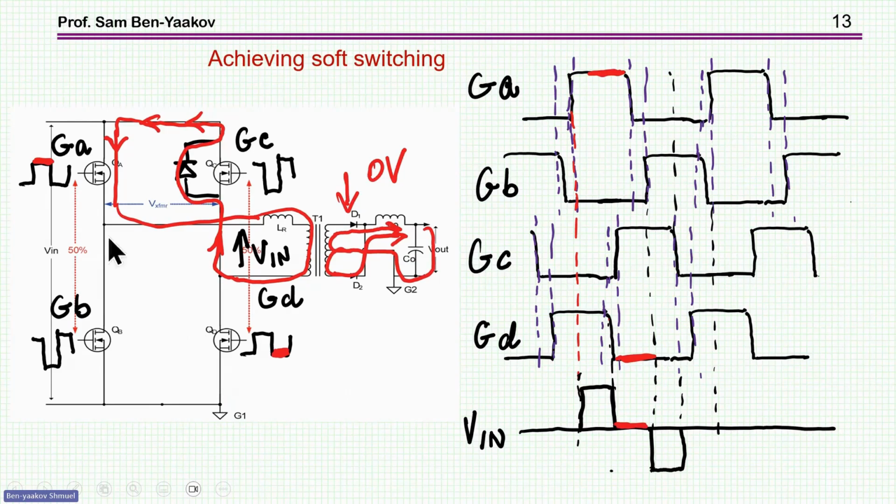So now this thing is locked. While being locked, very important to realize that the voltage at the output is zero, because now the two diodes will be conducting, and since the voltage here and here is the same, then the total voltage is zero. So we have zero voltage across this inner part here, and the inductor, this is the one that I was talking about and doing the whole job of this phase shift, is now actually causing the current to circulate here.